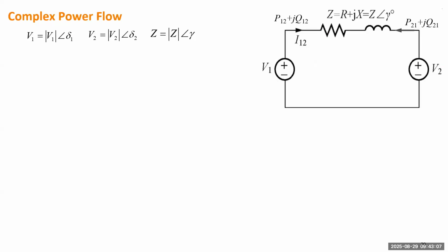All right, next we want to find a more general formula for this one. Later, using that example, we have this approximate formula. To use that formula, we can calculate power from one side to the other side. But that is based on two assumptions. The first, voltages are the same, the voltage will have the same magnitude, and also the transmission line doesn't have resistance.